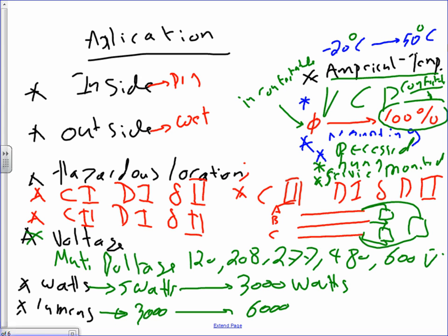Same with universal, maybe different manufacturers. I think universal is the same, but multi-voltage or universal voltage means you can bring any voltage to this fixture. A lot of engineers, guys, like that. The lighting ballasts are usually 120 or 277. Yes, but you can bring a ballast that burns at 120 or 208 or 277 or 480 or 600. 600 is not a whole lot used. They list what a multi is, guys. It covers almost any voltage. All you have to do is bring it and tie it in, and the ballast will figure out the voltage difference. A lot of engineers like the multi voltage.